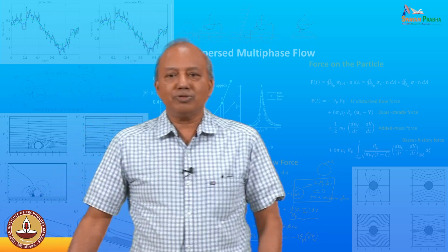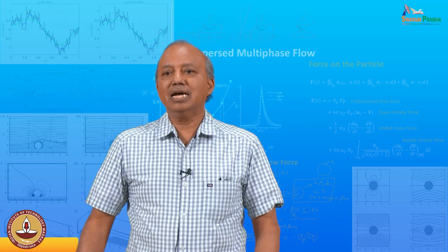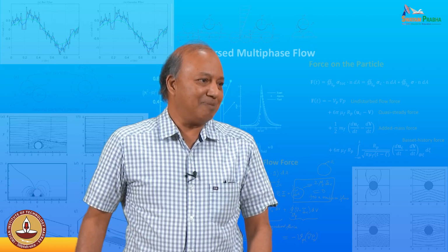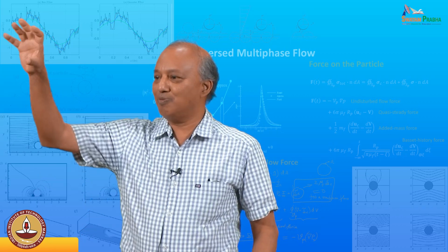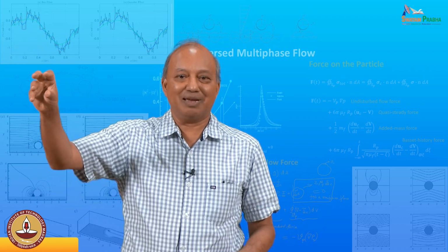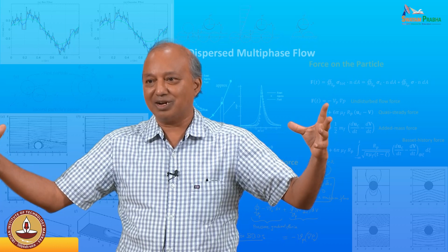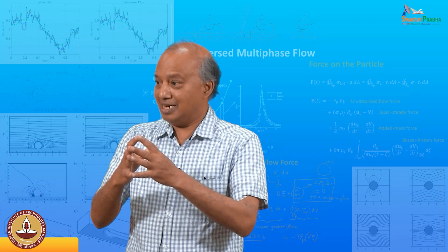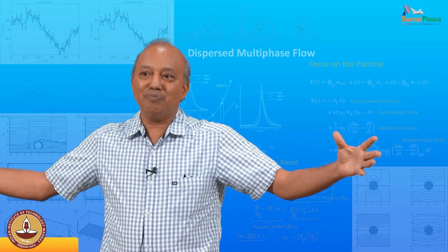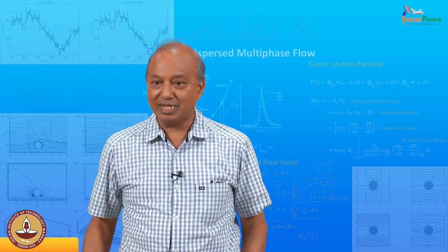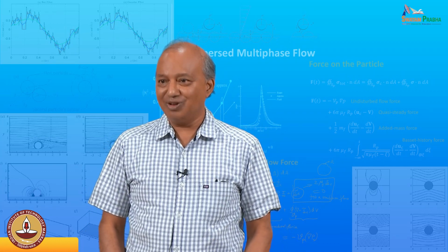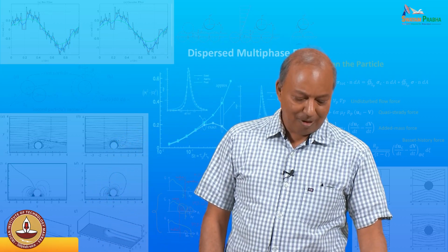Okay. So the rule of thumb I will tell is it needs to be much bigger than interparticle separation, because if you don't want to put a volume and no particle is there, or suddenly a particle, so it needs to cover several hundred particles in there to get a meaningful average. But on the other hand, if it's too big, then you may average over some of the structure that is there. By the way, this is an open question. There is no satisfactory answer I know of in the literature. Okay. So the volume averaging can be done.